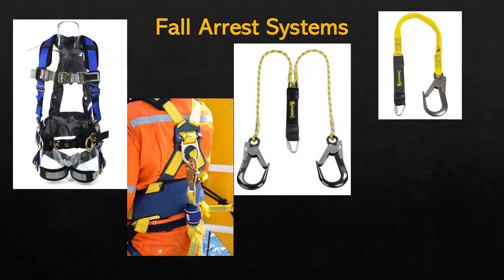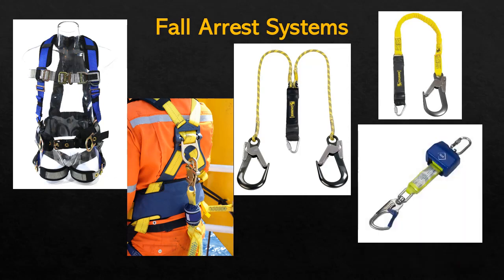Here's an example of a lanyard that is designed for 2 workers. And again, this is a normal and legitimate thing. You just need to make sure that whatever anchorage points you're tied to are actually rated for 2 workers. But yes, you can have multiple worker lanyard systems.